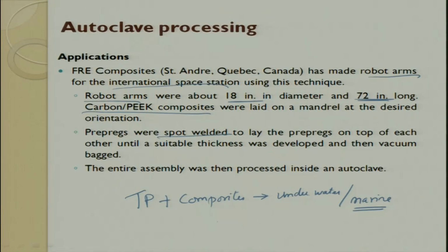So, autoclave is the other big process. Autoclave process, you can put it in this way, it is used for better consolidation. This consolidation helps us to push the volume fraction from 30%, now we have gone up to 50% in thermoplastic, which is a big challenge, right, and then it is used for only consolidation. So, autoclave is not a basic process in which you try to make the shape. Rest all things, you can make it through compression molding, tape prepreg process, or pultrusion process and come here for better consolidation.